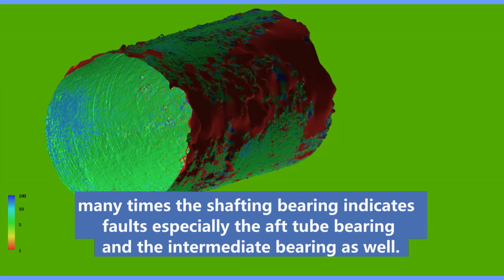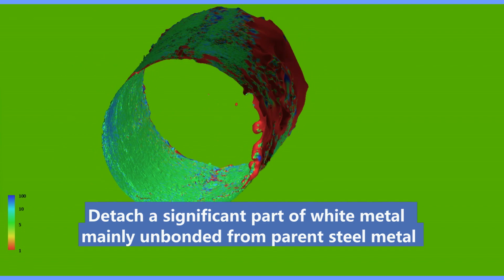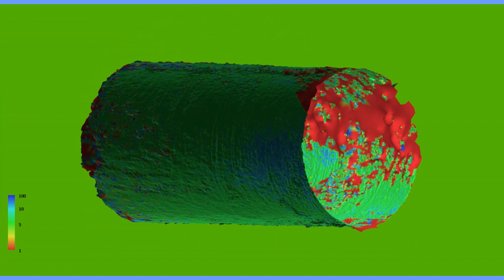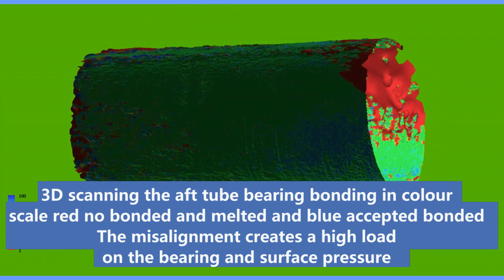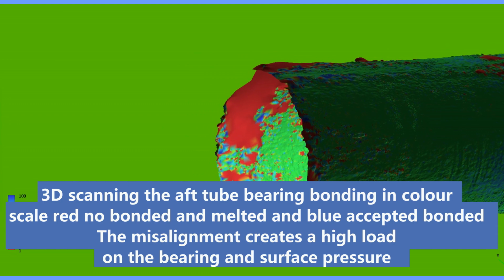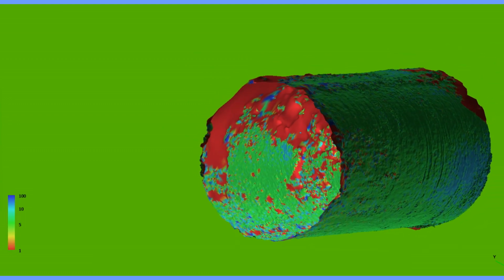the shafting bearing indicates faults, especially the aft tube bearing and the intermediate bearing as well. Two are the most common faults. 1. Detach a significant part of white metal, mainly unbonded from parent steel metal, and some melted due to excess surface pressure when the bearing reaction is over the classification society limits for bearing surface pressure.